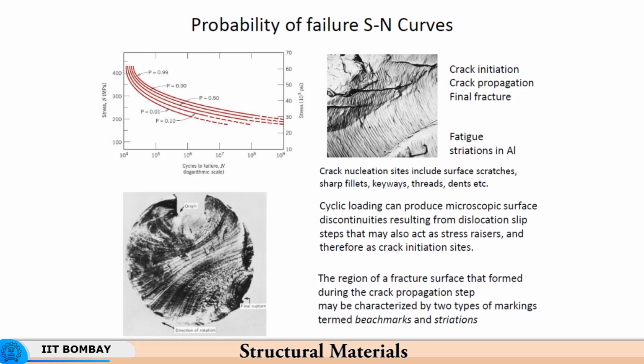But because the material is ductile and being subjected to cyclic loading, it is able to resist the advancement of the crack, because the load does not remain at the same level all the time, the load momentarily goes to a very high level. So the crack propagates by an increment, the load goes down and therefore the crack propagation is arrested, again the load goes up, again there is an increment, and this way, particularly when the load goes into the plastic deformation regime, there is dislocation slip taking place due to which some local plastic deformation would take place at those locations.